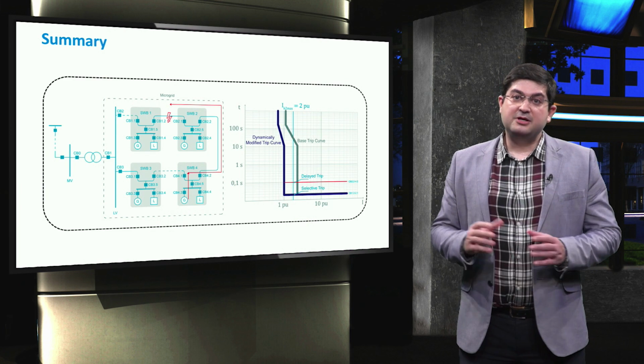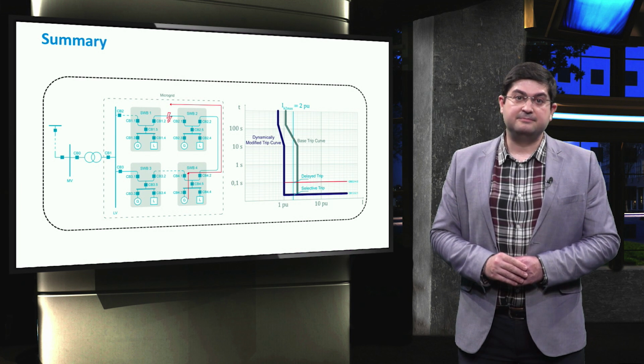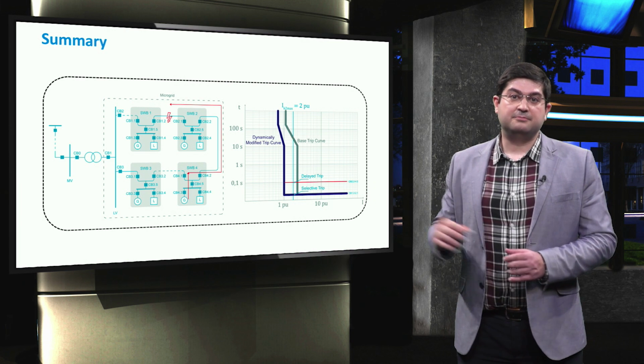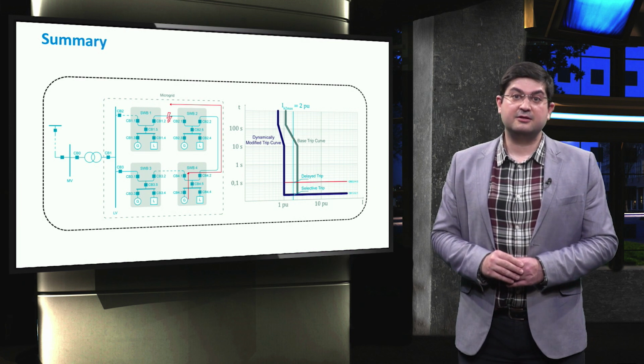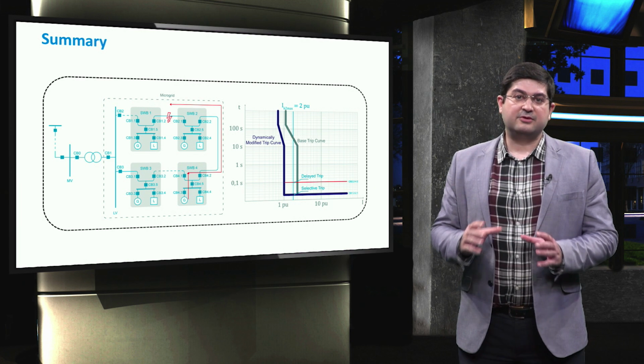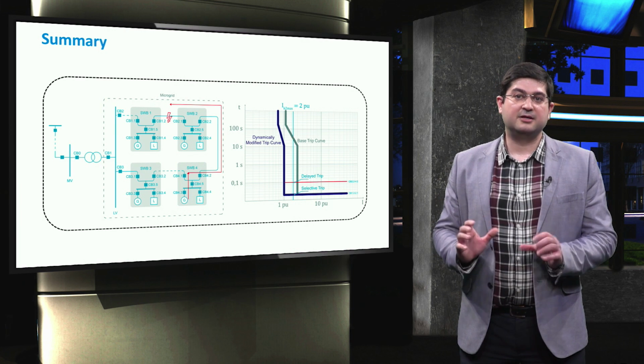In this video, we briefly discussed the adaptive protection for an islanded microgrid example. As the level of the fault current is relatively low in the islanded microgrid compared to the grid-connected one, we have to adjust the current time tripping curve of the relay in such a way that it trips much faster for a lower amount of the fault current.